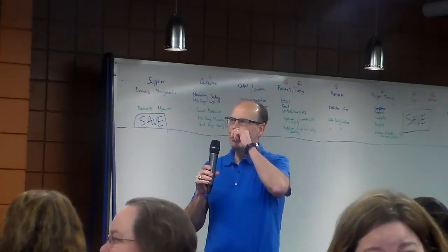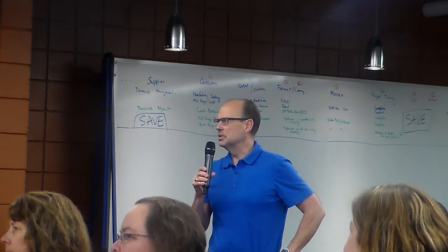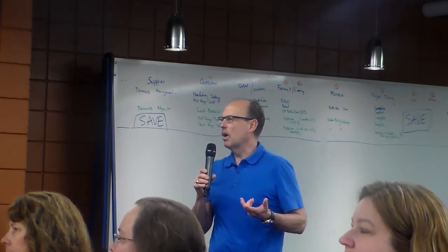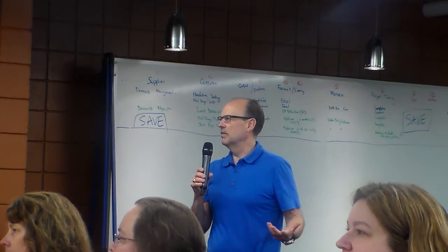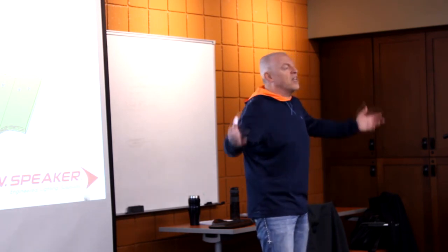So, question: on work lights, why are we using effective lumens, generally speaking, as a unit of measure, but in the headlight, we more often refer to candelas as being more relevant? What's the difference? The difference is really where the light is used. The work light is a generic, overall floodlight, so most people refer to lumens. More lumens, brighter, which is basically, yes.